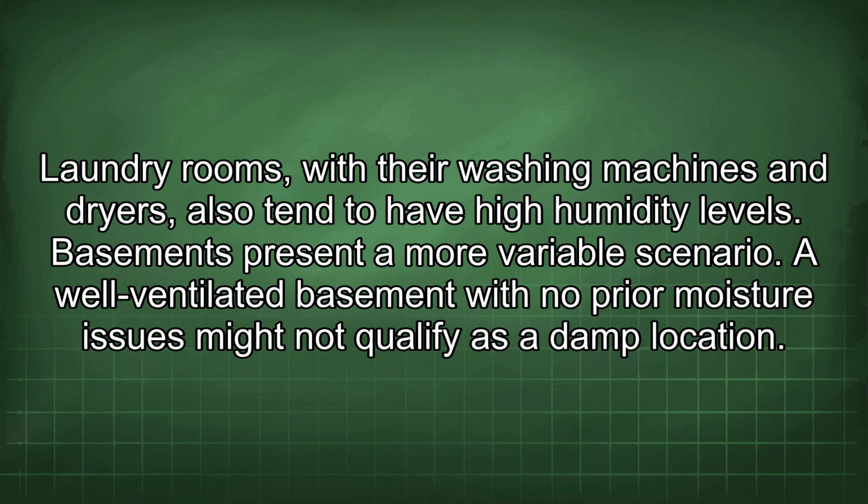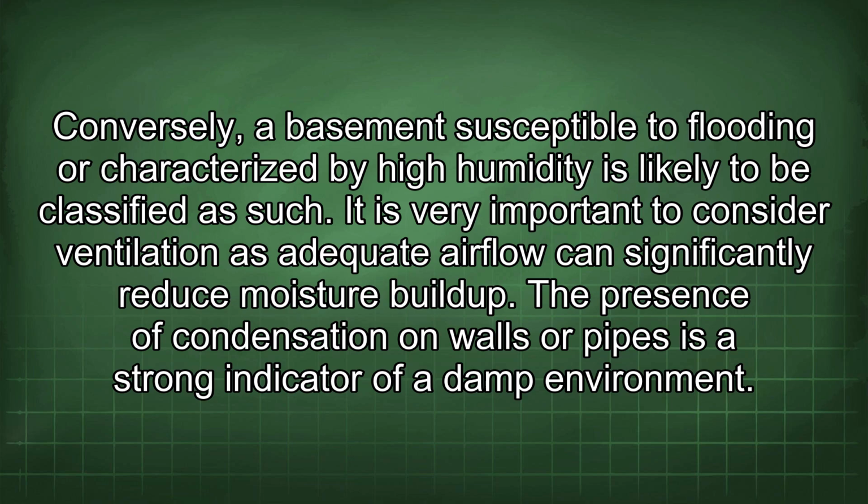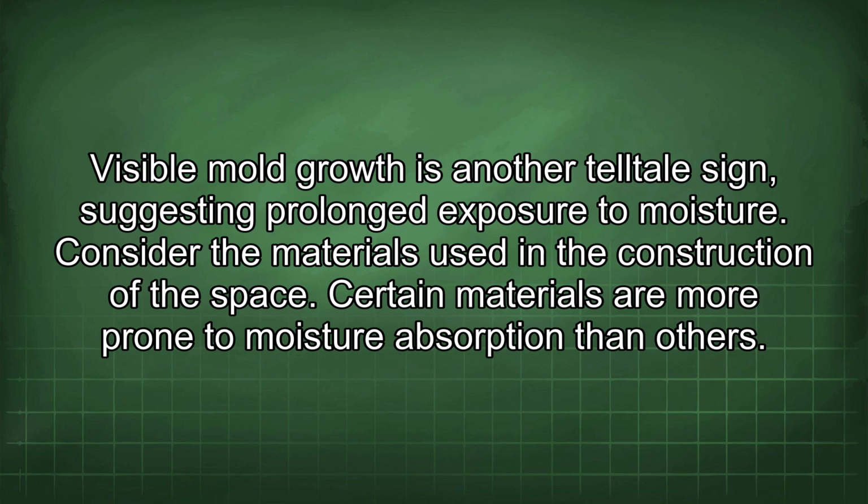Basements present a more variable scenario. A well-ventilated basement with no prior moisture issues might not qualify as a damp location. Conversely, a basement susceptible to flooding or characterized by high humidity is likely to be classified as such. It is very important to consider ventilation, as adequate airflow can significantly reduce moisture buildup. The presence of condensation on walls or pipes is a strong indicator of a damp environment. Visible mold growth is another telltale sign suggesting prolonged exposure to moisture.